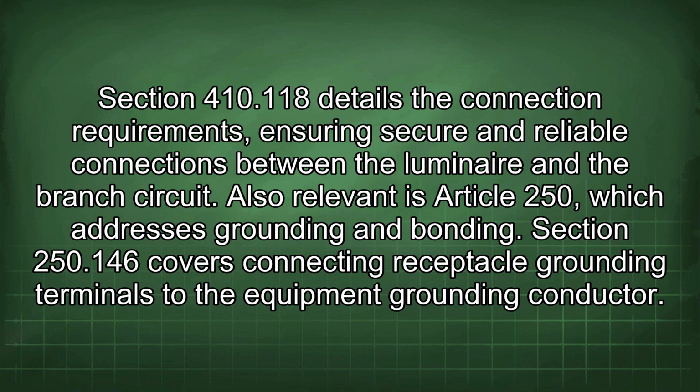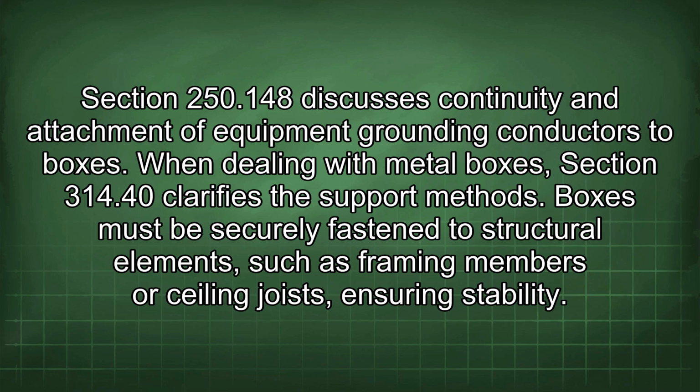Also relevant is Article 250, which addresses grounding and bonding. Section 250.146 covers connecting receptacle grounding terminals to the equipment grounding conductor. Section 250.148 discusses continuity and attachment of equipment grounding conductors to boxes.